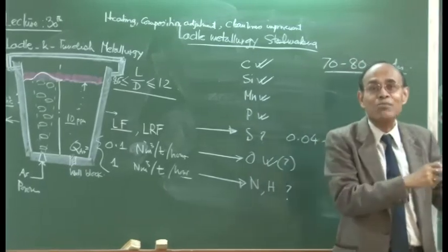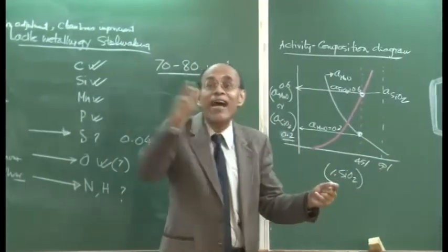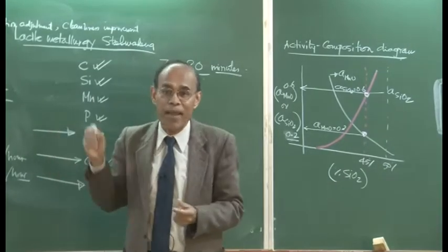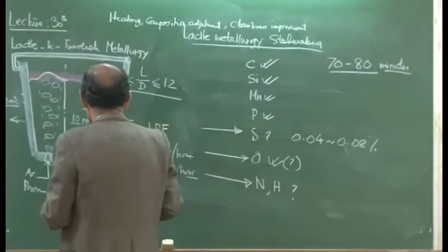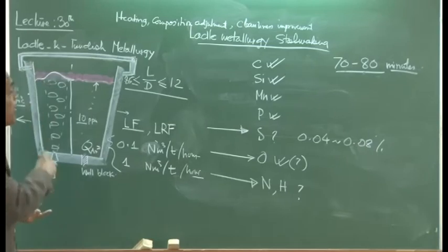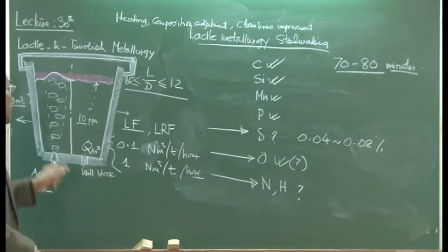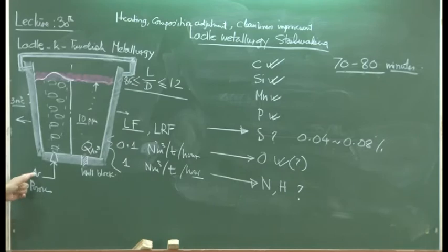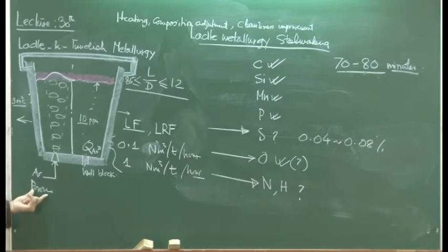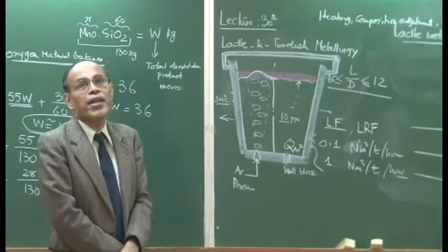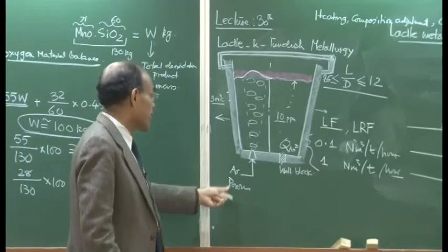So, the ladle cycles between what? Between the furnace and the casting pit or the casting bay, okay? And this frequency is about 70 times, 80 times, and up to about 120 times ladles can sometimes circulate, and then the ladle refractories do require relining. The porous plug is a replaceable artifact. So, it lasts about, depending on the quality of the porous plug, 7 to 10 hits or so.